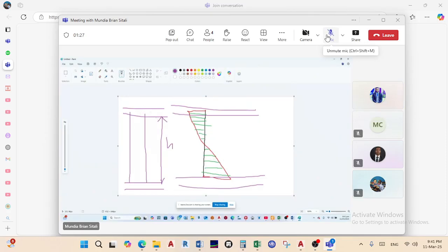So I was saying, if we take this as h, the height of the column, then there's such a thing where you say h over 4. In this region here, you want to have stirrups closely spaced, because in that zone you have quite high shear. Your stirrups, your links in a column, take care of shear. So this is the other h over 4.